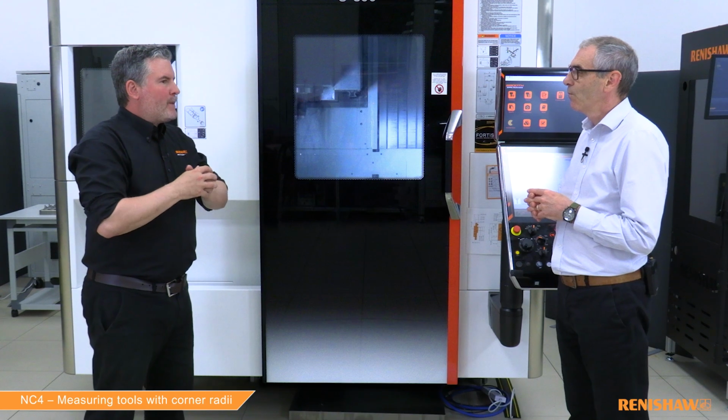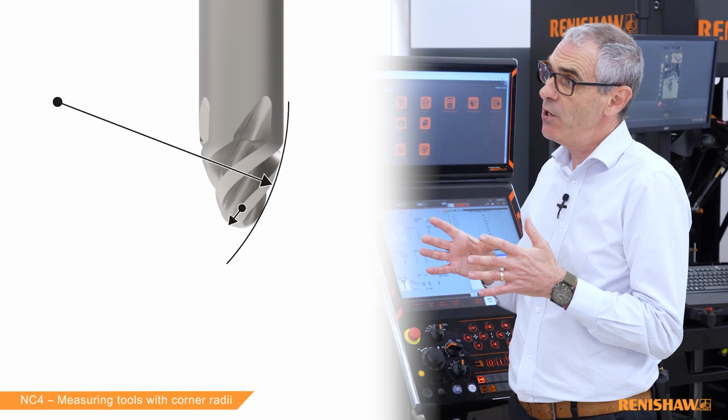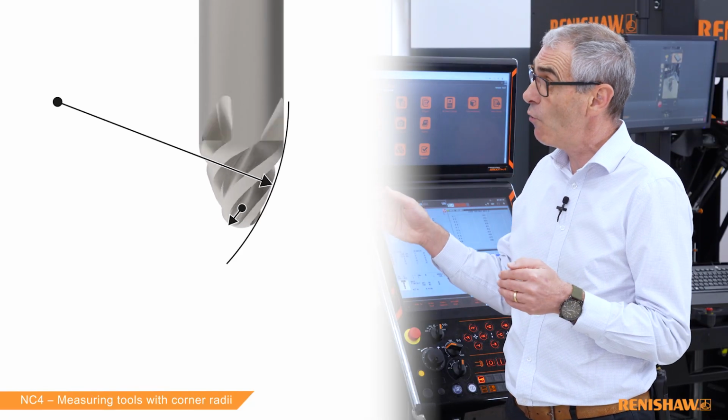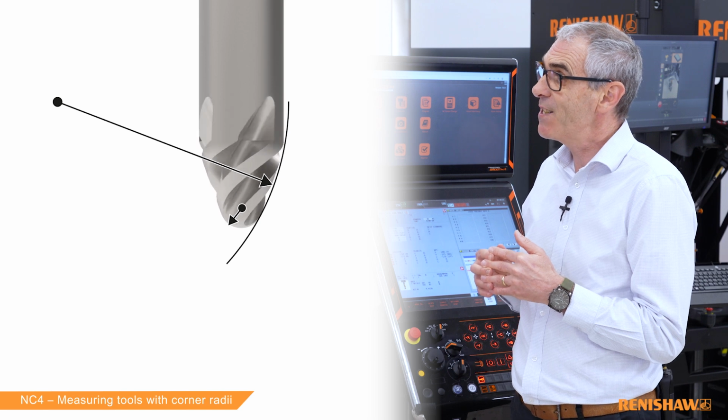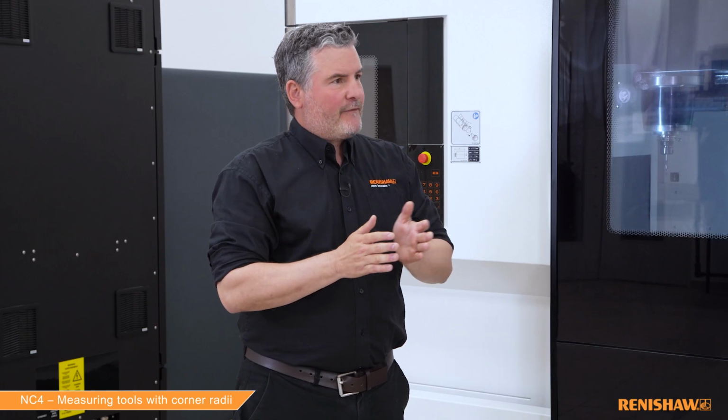With this 9867 cycle, we can measure bore nose cutters, we can measure cutters with corner radius, but what about barrel mill cutters? Unfortunately not. Barrel mill cutters use segments of very large radii. With cycle 9867, we need a full 90-degree arc. Okay, thanks for clarifying that, Ian.